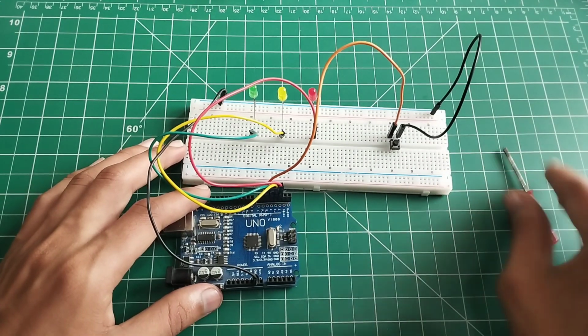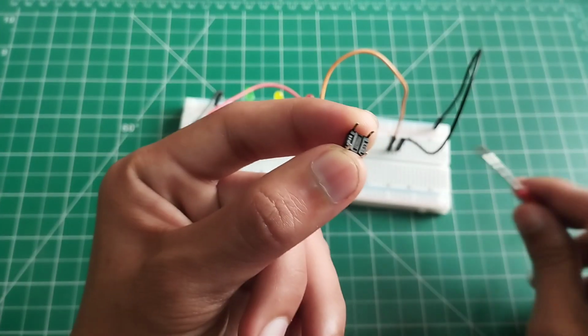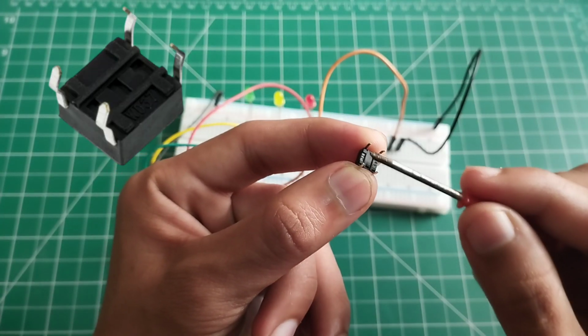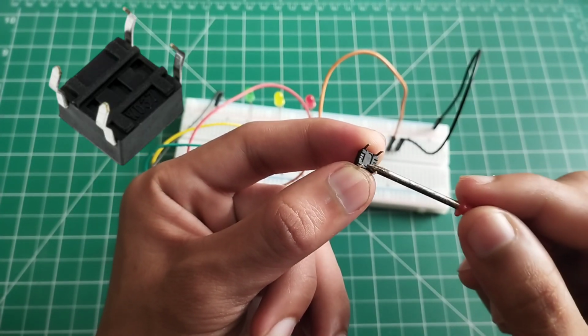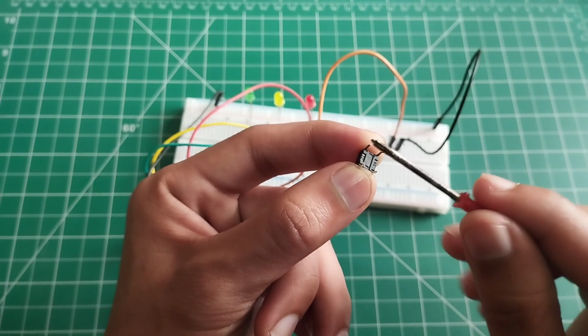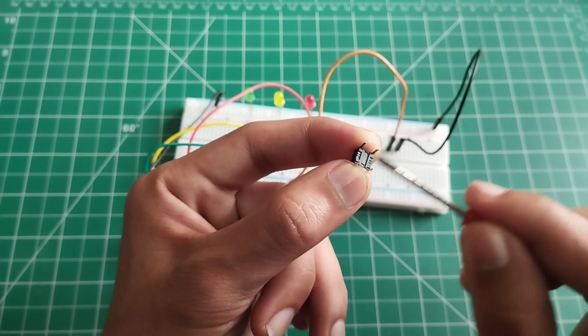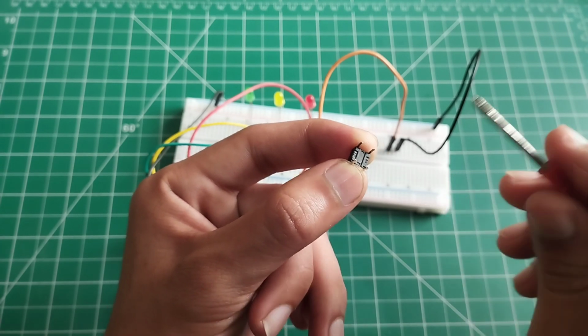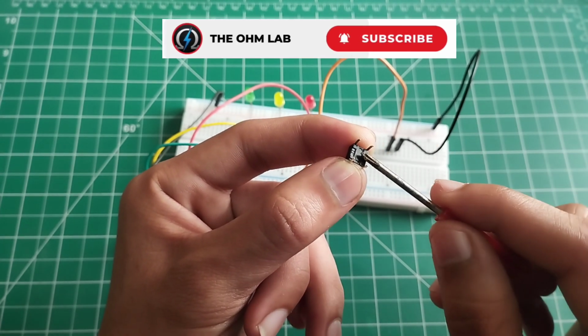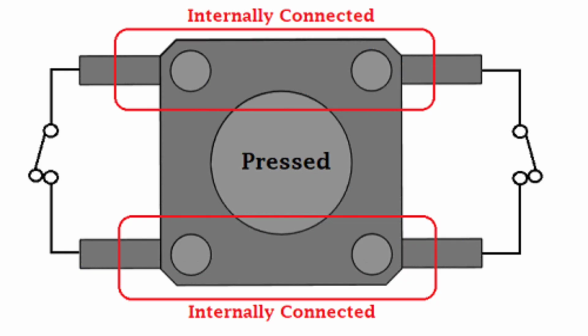Now coming on to this push button. So let me take this out, and you can see at the back of this push button there are two lines, this one and this one. Okay, so these two lines are showing that these two terminals are connected internally by default, and similarly these two terminals are connected internally, but these two terminals and similarly these two terminals are separated from each other. And when we press this push button, what happens? These two terminals get connected internally.